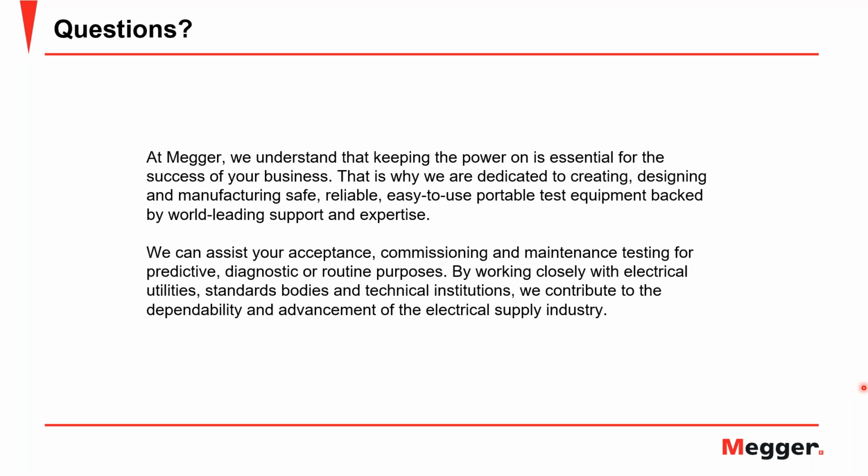Thanks, Mike. So yes, when a CT saturates, we do know that the primary current is not correctly mimicked on the secondary side, and that is what the relay reads as a current. Obviously for a directional protection, since the current can be used as an operating quantity or even a polarizing quantity in some instances, it's very important for that current to be accurate.